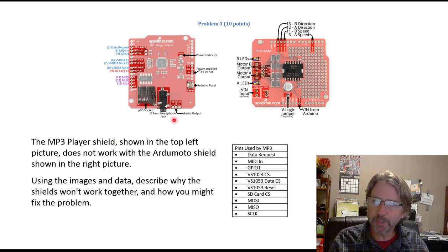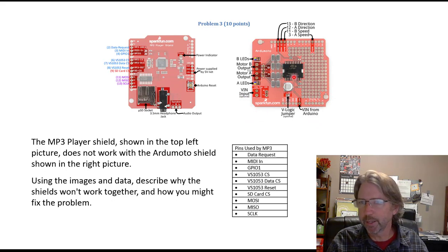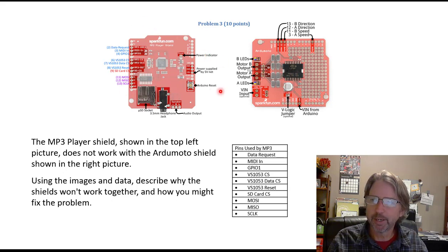And so what might happen is you want to use this to play the sounds, and then maybe you want this, which is an L298 board. Like, we're using a slightly different board for the class. Most likely you didn't buy this one. But this is in shield format with that motor driver chip. And if you stack these on top of each other, if it used to work, it won't work anymore. So if you tested out your sound and then add the motor, it's not going to work. If you test out your motor and then add the sound, when we stack these on top of each other, they don't work. So this was an old midterm question.